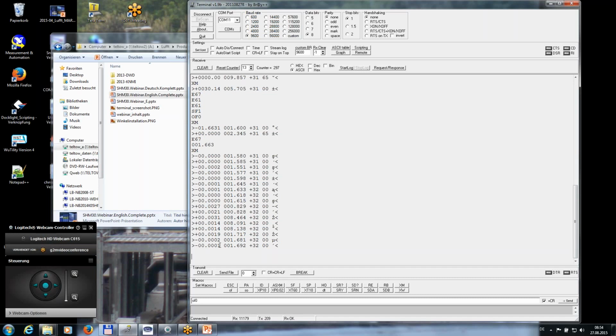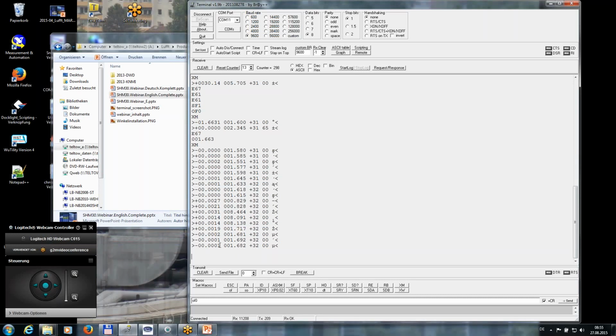So it's within the tolerances. This method which I've shown you with these 2 photo plates is the standard procedure which you can always do very easily in the field. Check the values which come out, and this of course helps a lot to give a first estimation if the sensor is correct or not. It gives you an idea. When it's within 10%, it's quite good. If it's within 20%, it's still acceptable.